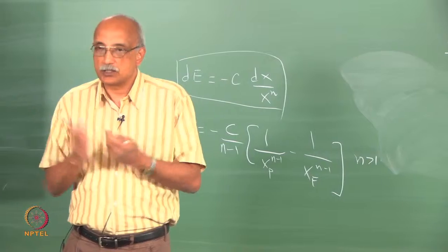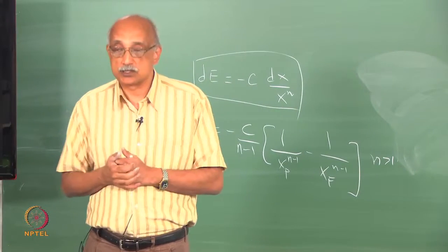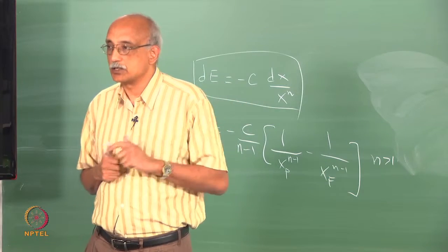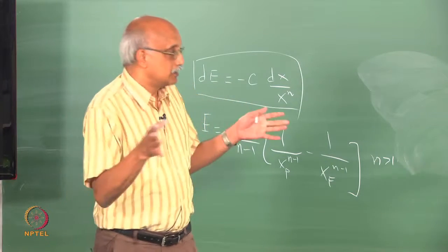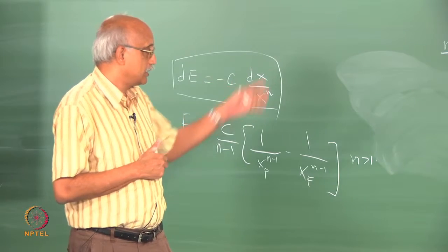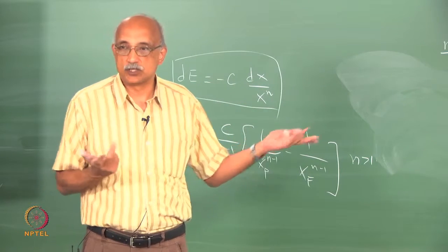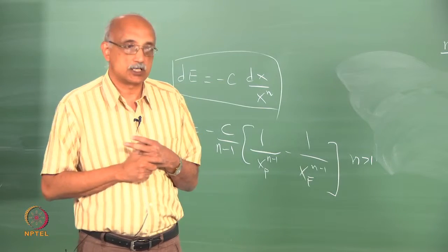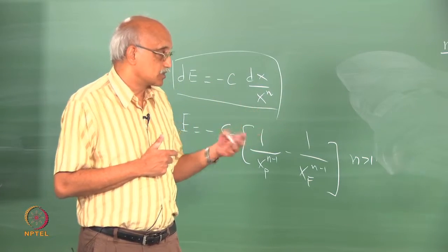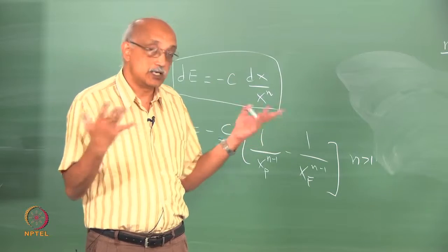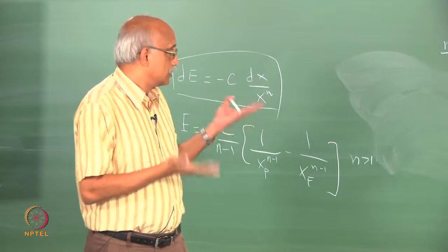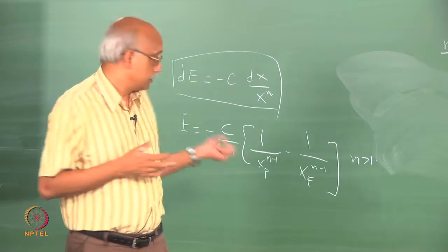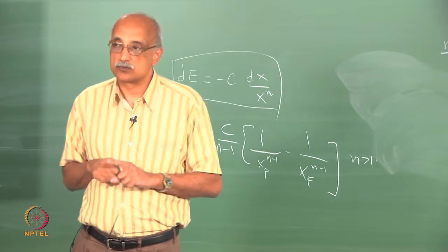If you look at the data that you will get from your own experiments, you will find that there is a pretty good fit to what these laws are predicting. Typically, the exponent you will get clearly will be somewhere between 1 and 2 when you actually do the experiment, because that is a range in which scientists who have done this for many years have established n equals 1 to n equals 2 as a range in the energy efficiency law for size reduction.